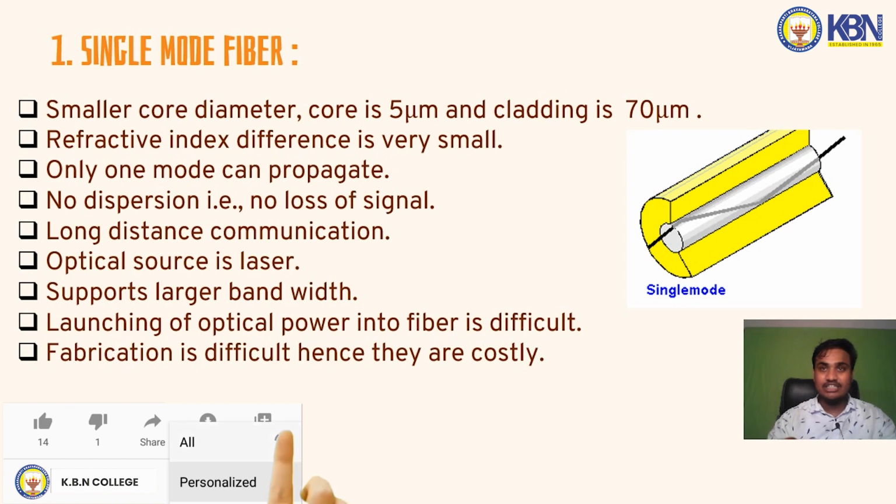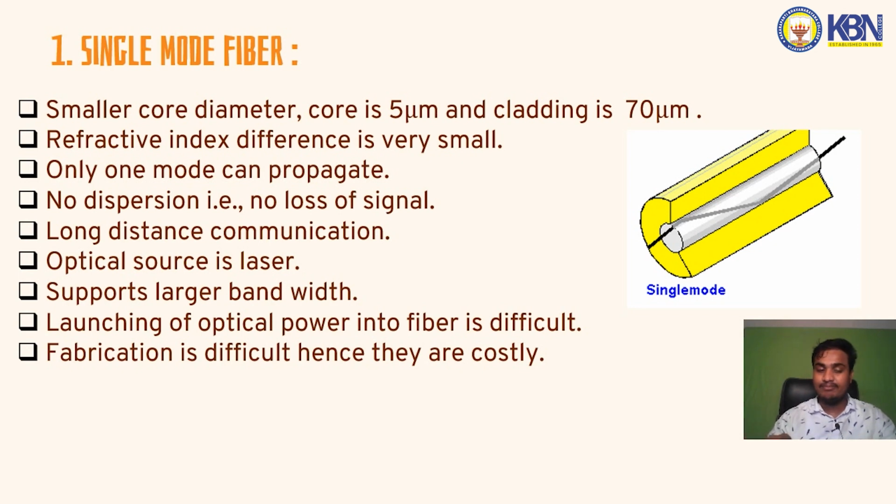The launching of optical power into the fiber is difficult. Why? Because the core diameter is small. Now coming to the fabrication or manufacturing of single mode fiber, it is difficult. Why? Because it has a smaller core diameter, hence they are more costly.